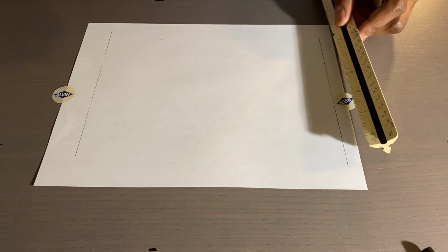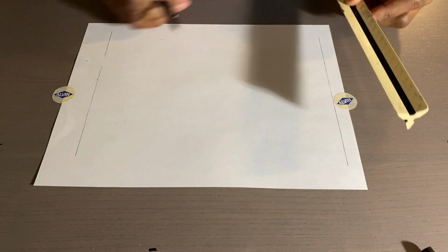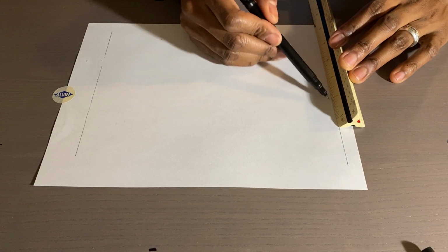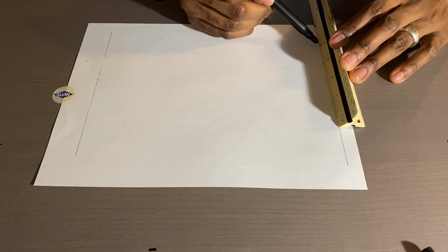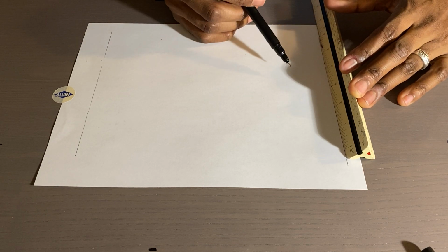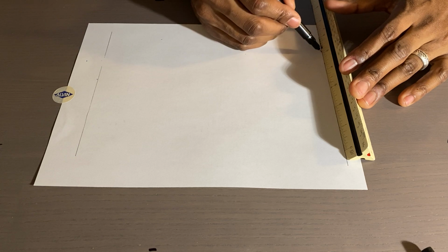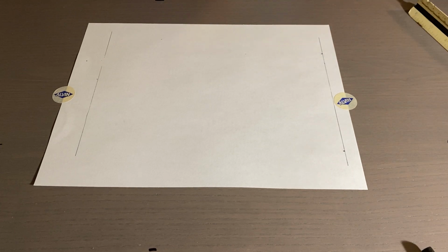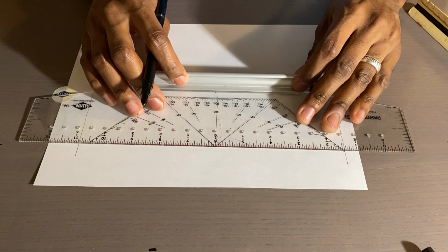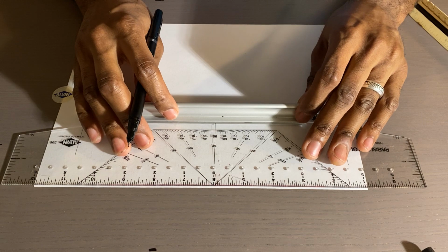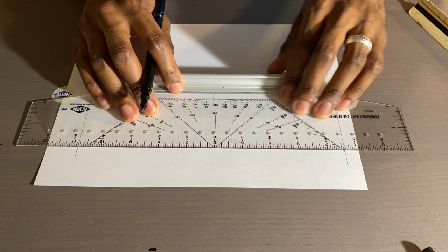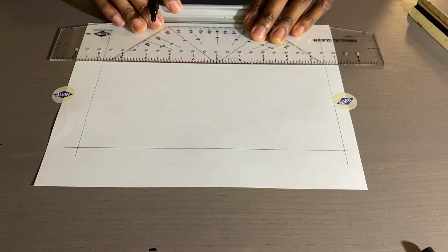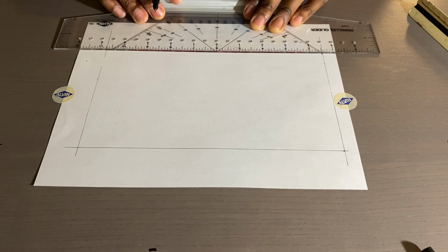Now I need to establish the width. So again, taking a 1/16 of an inch scale, and that's 10 feet, 20, 30, 40, 50. So I'm trying to center it in the space on the sheet here. So that's 50. So that's going to establish my width. I take my little sliding ruler here, try to make sure it's parallel, just drag it down, and then just do a little light line there. Again, you can do this with a pencil if you feel more comfortable doing that. That's fine.